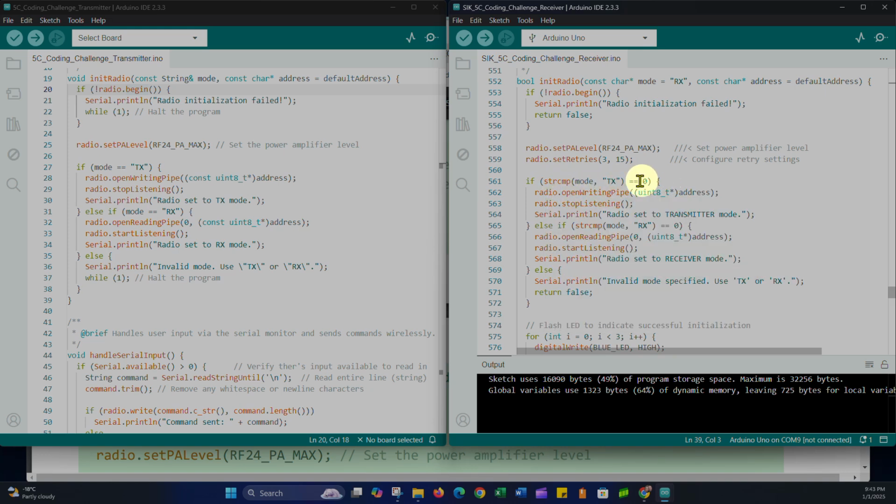So this is associated with C-style strings. Because in this case I'm actually using an Arduino string type, the equality operator works with string type, so I can simply go if mode equals transmit. So these differences in code are literally doing the same thing. I just wrote them differently, because I wrote them at different times, to be honest.